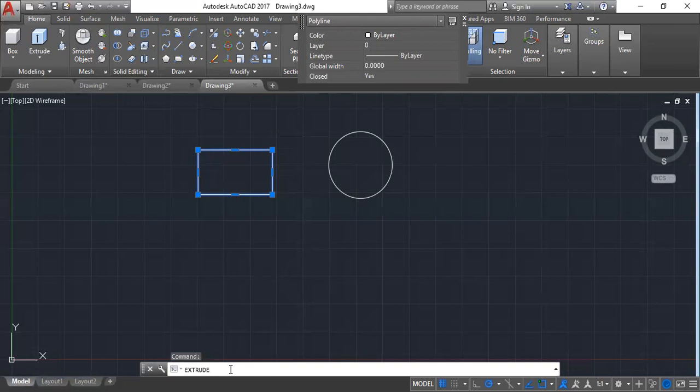What's going to happen here is this. It's now going to ask you some questions, like what height of extrusion would you like to add? You just need to specify the height of extrusion, and then when you press enter, automatically that height will be used as the depth for the shape that you've already selected. That's what is supposed to be done.